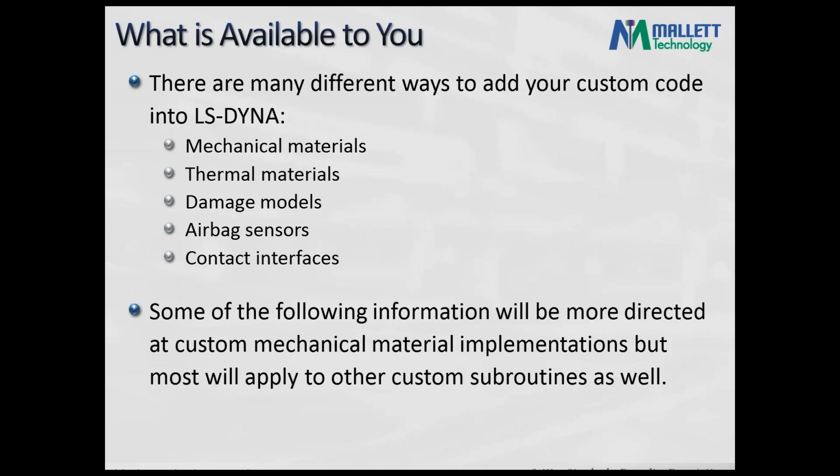There are a lot of different ways to customize your LS-Dyna materials and otherwise. You can have different mechanical laws, different thermal laws for how they conduct and store heat, different damage models for fatigue and fracture, different airbag sensors, going back to the auto industry thing, and different ways to define your contact. Although it has all these options, some of what I'm going to say today is more applicable to the mechanical materials side of things as opposed to the rest of them, but most of it should apply to all of these topics.